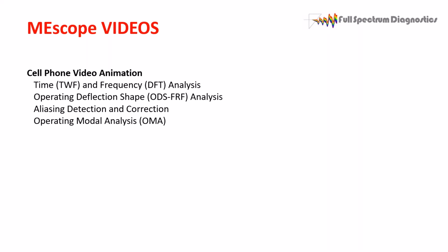So now instead of having a limit at 120, we can have a limit at 240 and see where all those show up as harmonics. So if there are other things going on, we should be able to detect it, things at a little higher frequency. But remember, if we're doing operating deflection shape or discrete Fourier transform, they're all phase related. So don't forget that.